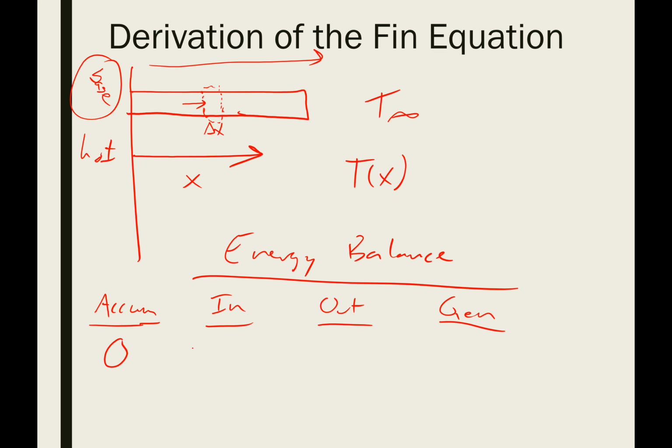That is going to be coming in by Fourier's law, so minus k dT/dx. And let's assume this thing is square in shape and that it is delta y deep and delta z tall. So we could just have a delta y, delta z. Okay. How is energy getting out?